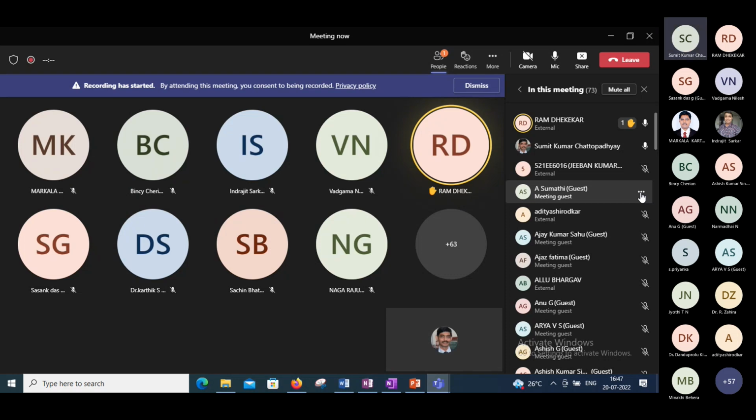On the other side, the converter implementation cost will go up. Still, a 250 level or 251 level inverter is there in practical operation, but that is not for such low voltage. That's for HVDC application.